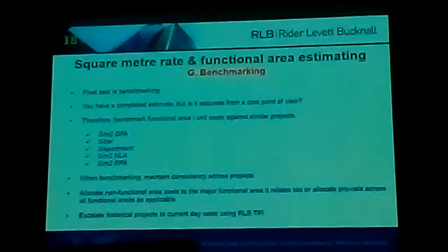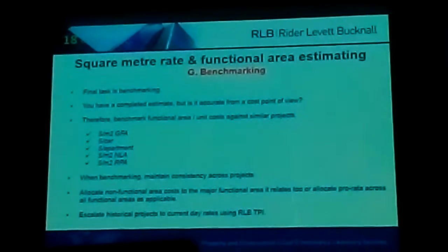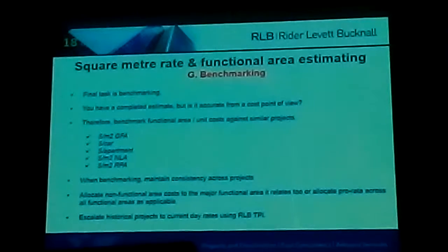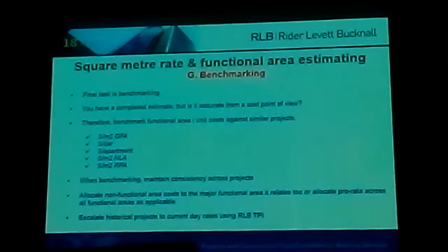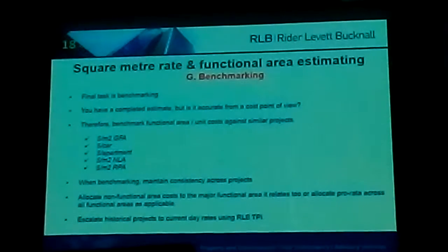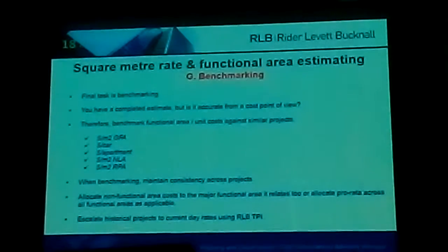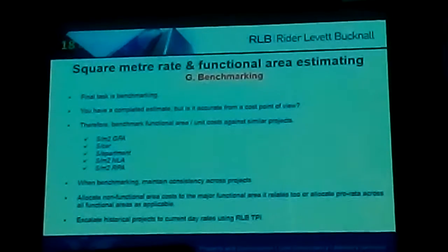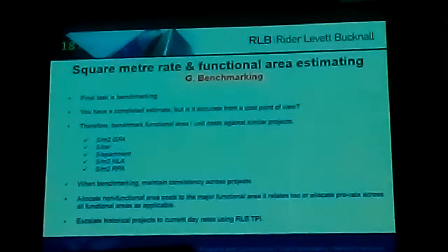When benchmarking, maintain consistency across projects. Therefore, exclude demolition costs and/or specific project-related items of significant cost. Allocate non-functional area costs to the major functional area they relate to, or allocate pro rata across all functional areas as applicable. Escalate historical projects to current day rates using RLB TPIs.